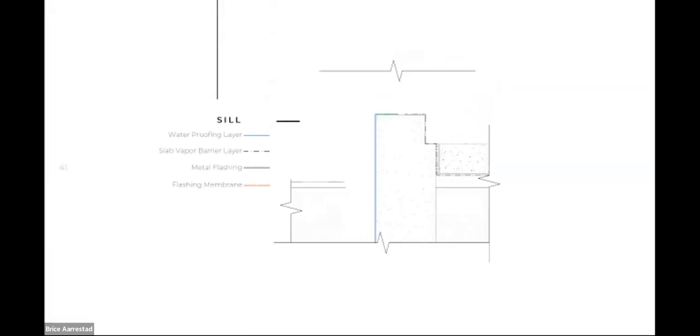The sequence of this can change depending on your construction sequence, but in general, this is the principle: you have flashing membrane that's protecting the opening and an air barrier membrane that is connecting to the timber curtain wall. And those principles aren't that different from the sill. Some of the layers may be different.